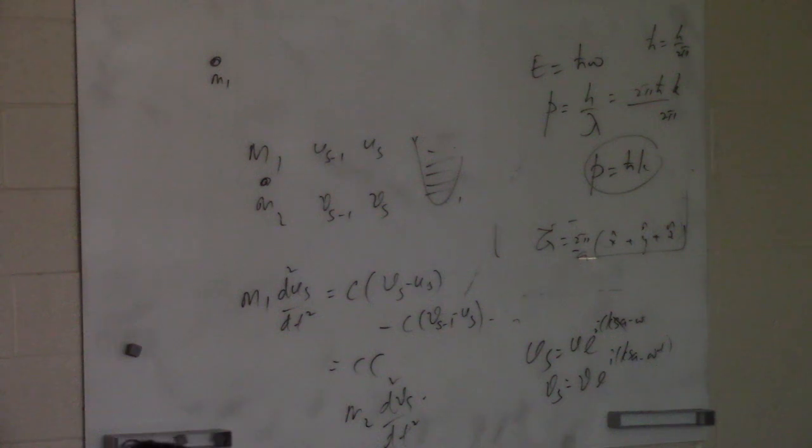What's the left hand side? Oh, this is called the figure of merit, ZT factor. That's how good your material is. So this is the important thing. Later I will talk about this one. We need to reduce K. Reducing K means you have to introduce more and more phonon scattering.